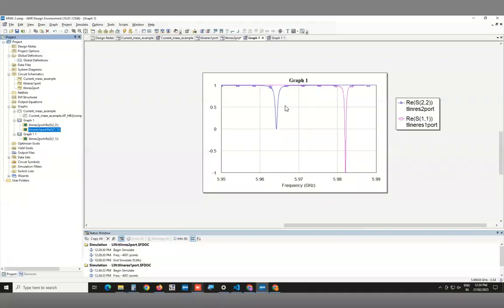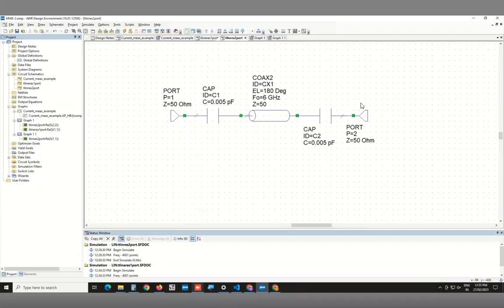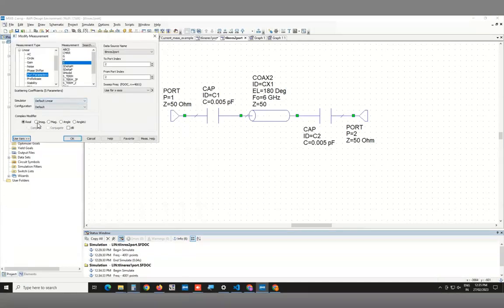This is what happens when you have a dissipation, apparent dissipation in the resonator when measured from one port. So here the dissipation is not happening in the resonator, but it's because there is a path for the energy to go out of there. So from perspective of one of the ports, it looks like there is loss. So the fact that the real part goes from 1 to 0 is actually a way how you know that, okay, there is some dissipation. Of course, that also reflects in the fact that the magnitude now shows a dip as well. There is similarly a change in the imaginary part as well.